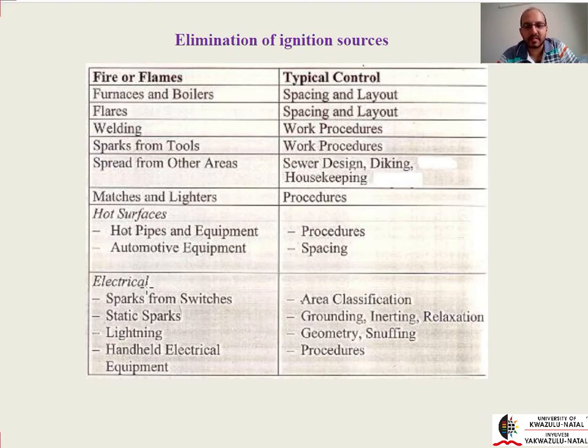With electricity, of course, with our modern factories, we need electricity all over the plant. So we can't actually reduce that through spacing and avoidance and procedures. Well, we can use some procedures, but essentially electricity has to be in a number of places. And it's controlled typically through area classification. Okay, so just intelligent grouping of certain units and area classification.